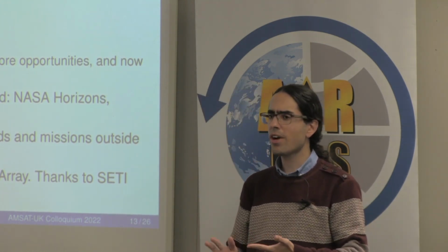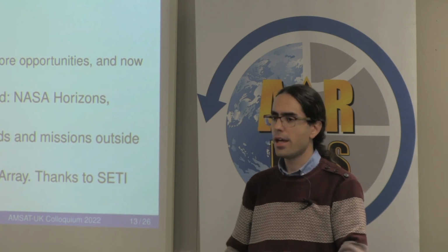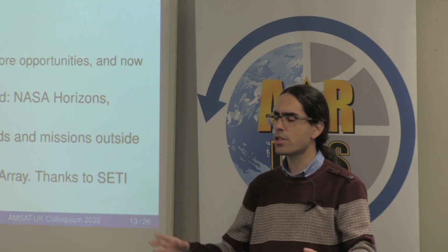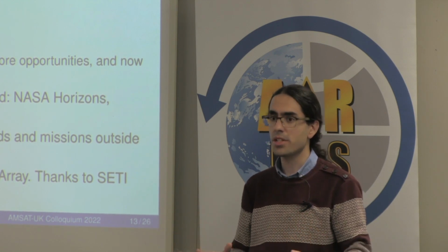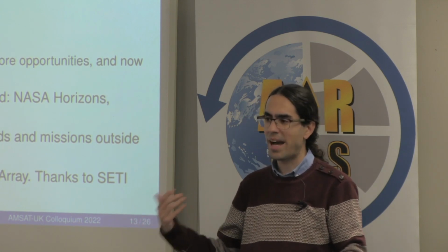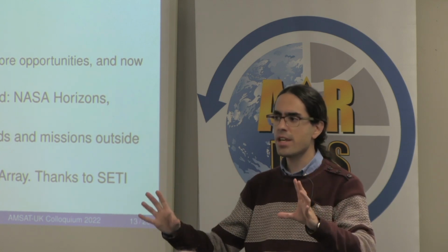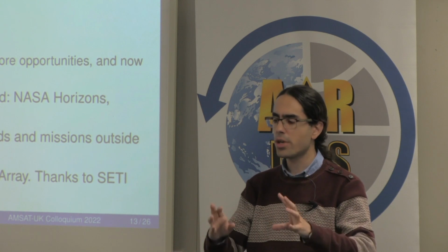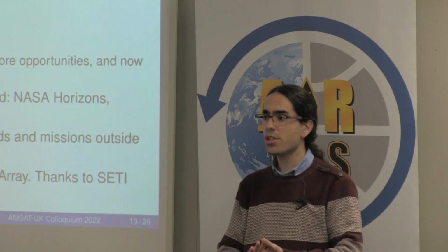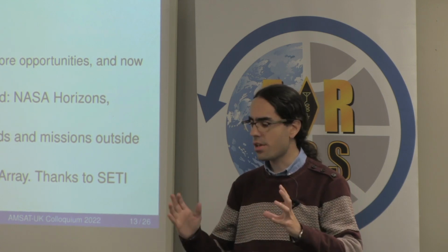And maybe some of you have heard about amateur DSN. DSN means Deep Space Network. These are people who have their amateur stations at home. Maybe it's a 2-meter dish or 1-meter dish or even a 60-centimeter dish, and their S-band, so 2.2 gigahertz, or their X-band, 8.4 gigahertz receiver, and they try to receive probes at Mars, at Jupiter, and so on. So there are people who love to do this, and traditionally this is done only by detecting the CW carrier.